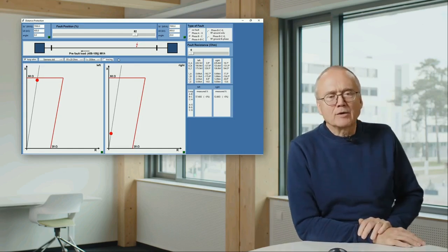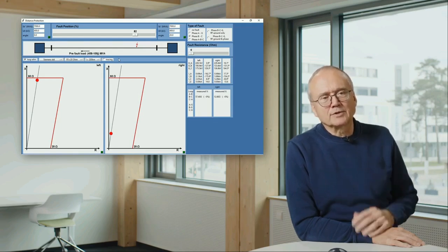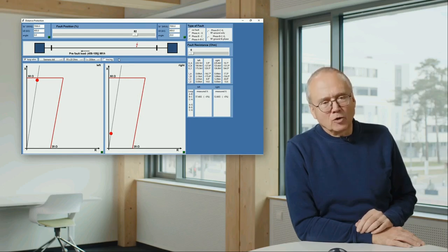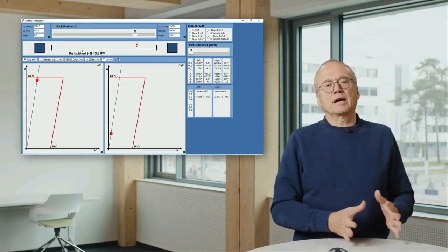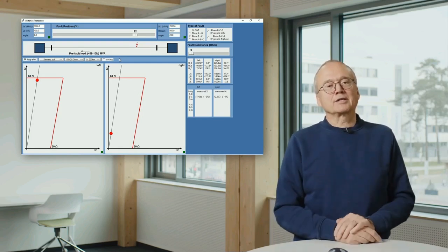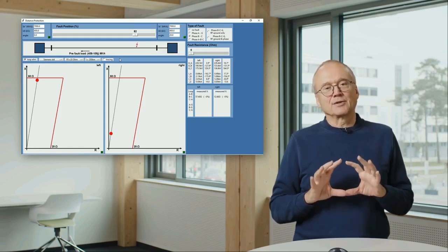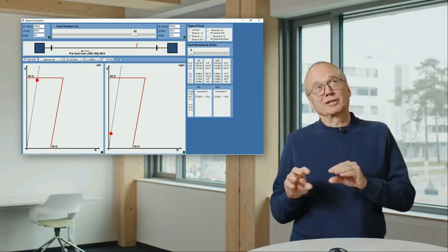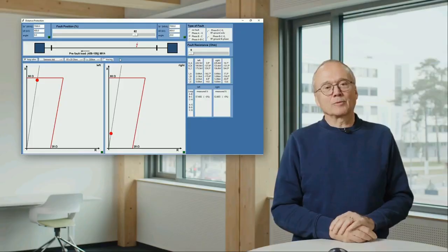And one thing we implemented and we really recommend is the so-called RMD method or reactance method in our protection relays. That means in our protection relays you have the possibility to activate either the conventional algorithms, as I showed up to now, or you can activate the RMD method, which then solves to a certain extent this problem. Unfortunately, you have to set again a few parameters. Sorry for that, but the algorithm requires that.